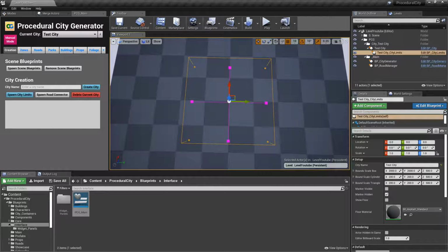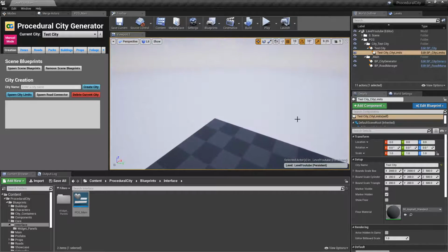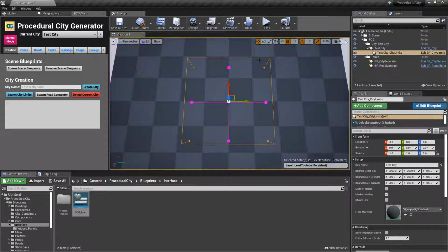And a nice little tip, if you hit Control and one of the numbers on your keypad, in my case Control 1, you can just press the 1 key or whatever number and the camera position is saved. That's really handy if you want to quickly navigate your scene. So I've already set up my camera here at the top. We want to make sure that we see everything generating.